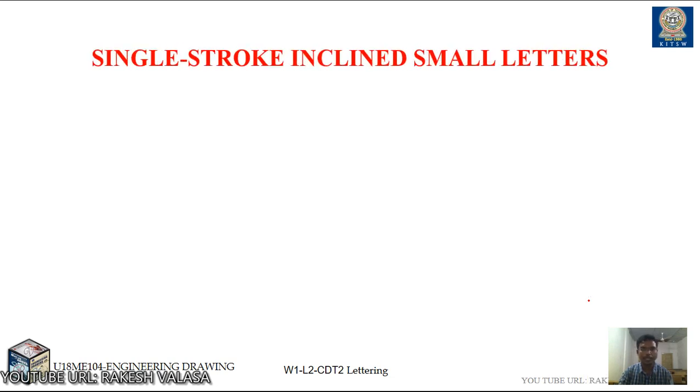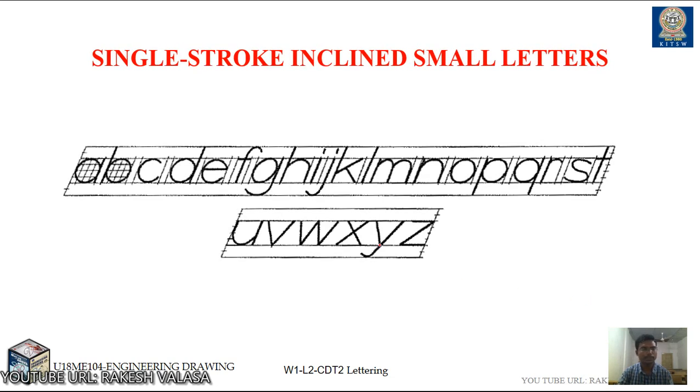Single stroke inclined small letters. This is similar to single stroke vertical small letters. The major difference is that this inclination makes an angle with the vertical line of 15 degrees, or with the horizontal line of 75 degrees.